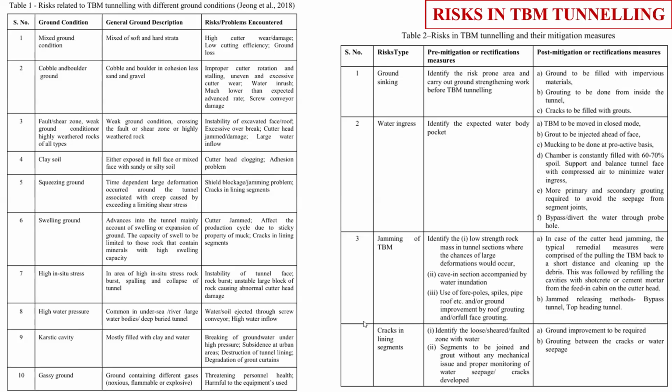So one problem of the TBM is that if it is designed for a particular type of ground, in a mixed ground condition it will have lots of problems. In hard rock, it will have a very high cutter wear rate. In soft ground, it will have a very huge volume loss. If there is a high groundwater condition, there can be more groundwater ingress inside the TBM, so you need a high face pressure. The main problem is in the rock.